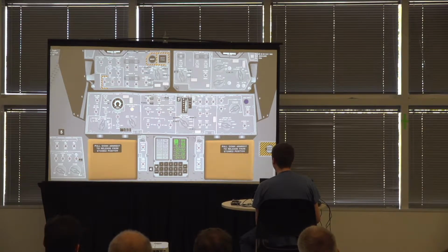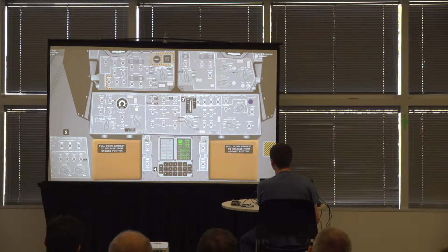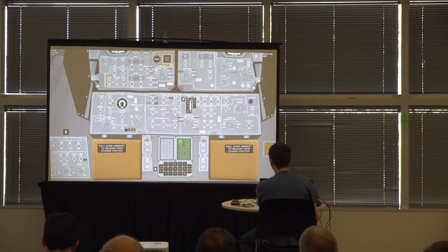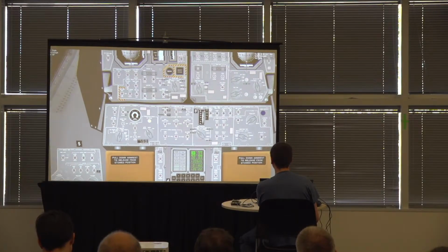So what I'm going to do is verb 57 enter, and that allows the AGC to start using the measurements from the landing radar. And now if I do a verb 16 noun 68 enter, we'll see the delta H slowly count down as the AGC slowly incorporates the radar readings into its idea of where we are. So this should count down to within 10 feet or so. Okay, so we're looking good on altitude now.